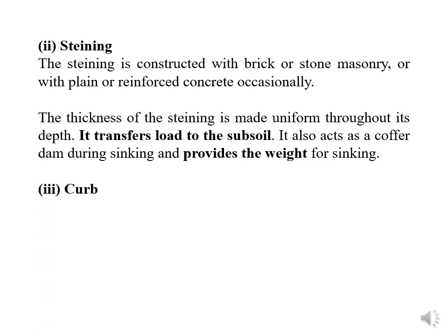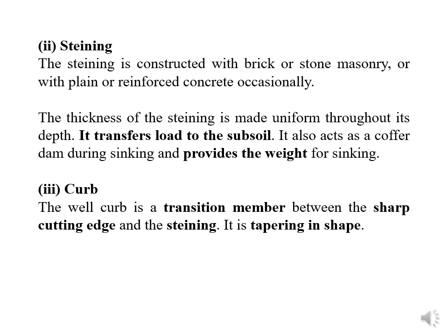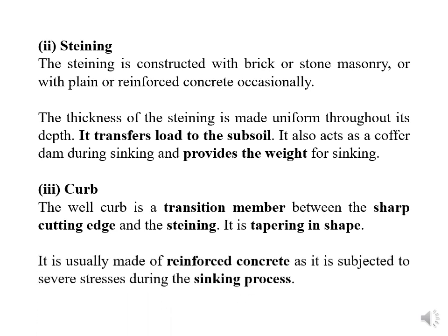Next is the curb. Curb is normally a transition member. Transition member means the connecting part in between the steining and the cutting edge. It is normally tapered in shape. It is usually made of reinforced concrete and is subjected to severe stresses during the sinking process. So the curb is made up of RCC.